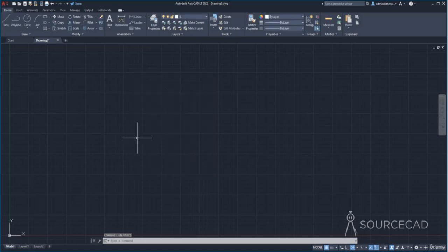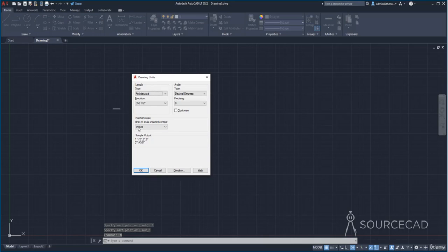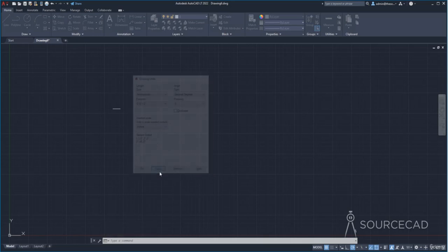Let's click OK, and we can now directly add distances and other values using feet and inch. Let's do that. So I'll go to line. Now I'm going to make a line of length 1 unit. So I'll simply type 1 and enter. And AutoCAD will make a line of length 1 inch. Why inch? Well, because if you go to unit, you'll notice that it is inches. The insertion scale or the unit is inch.